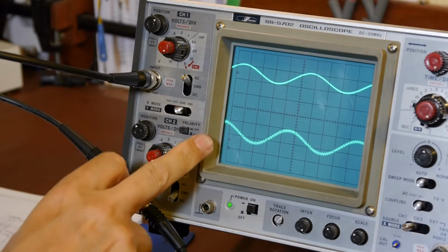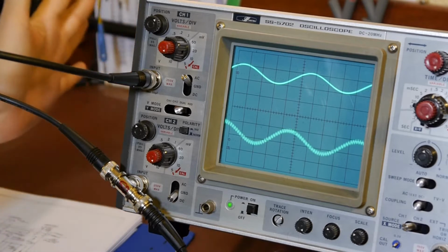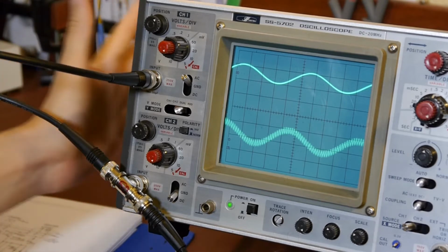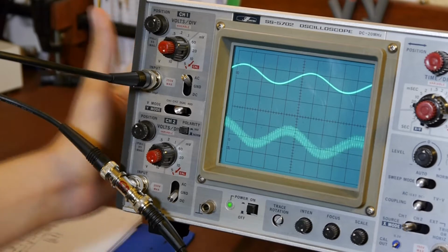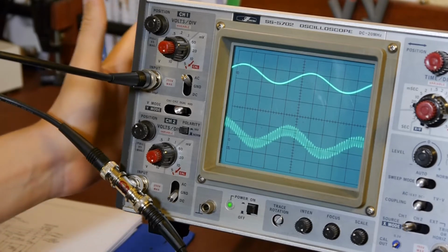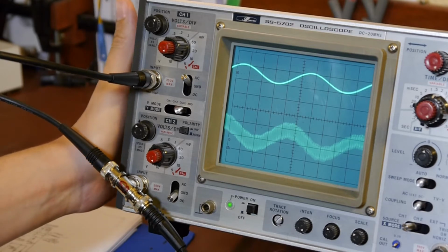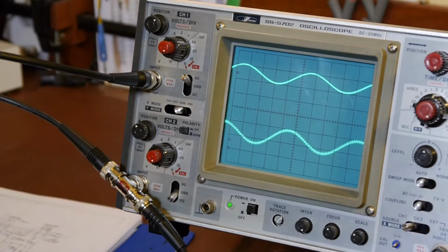It's interesting to see that there appears to be a lot more noise on there, and I think that'll be 50 Hertz noise. But I'm not worrying too much about that at this stage, because I'm just wondering if it's more of a screening issue than anything. Because I notice if I put my hand near the scope, you can see that I'm actually coupling noise into it. So yeah, there could be a problem there, but it might just be more of a fact that it's a very high input impedance circuit. So we might come back and have a look at that.